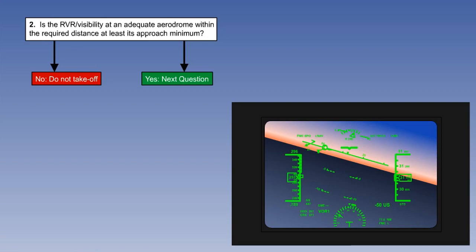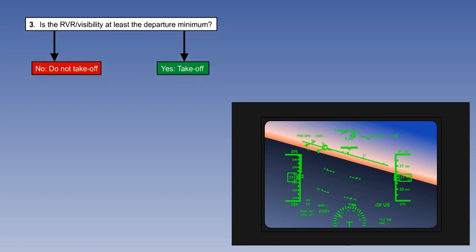Suffice it to say that for the MRJT operation, a takeoff alternate must be within the distance commensurate with 1 hour's flight time at the one engine inoperative cruise speed in still air, and at the aircraft's actual mass. If an adequate takeoff alternate can be nominated, the RVR, or visibility minimum, reverts back to the initial tabulated value, that is, in the case of the MRJT, 150 metres.